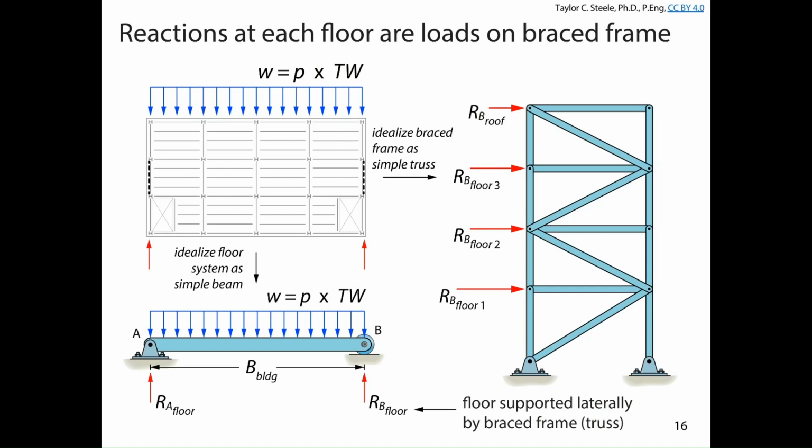And what I mean by that is if instead your brace frames were inside, they're not always on the outside face. In that case, I would draw this as having a pin and a roller, something like this, and it would have a simple span and some cantilevered spans, and the statics of that problem would change ever so slightly. Okay? In this case, I guess the forces here and here would be more or less the same, but the load isn't always going to be uniformly distributed over the length of the beam or the floor, and we'll talk about that in a second.